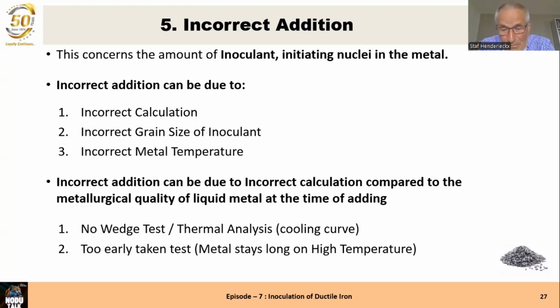And you are gambling like in the casino. The second is too early taken tests, because you can do a thermal analysis test, but if you do it and you wait later 10 minutes before you go on, or you wait 20 minutes before you go on, it can be that in the meantime your metal is totally different than at the time you took the test. So pay attention for that.